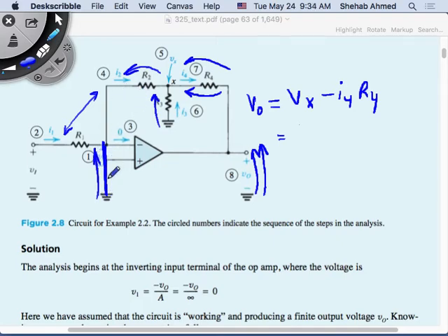This is 0 here. I was thinking, right, so making R2, R4, R3, because there is a Y connection. You can convert Y to delta, yeah, and make it one resistor instead. You can convert to delta and then it becomes like this, right? Then the output voltage is equal to the voltage across this resistor only. So you can convert delta to star.